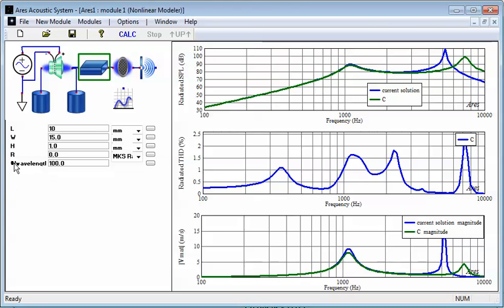That should be read as number of discretizations per wavelength in terms of the port. So if the wavelength is very long, you don't need many discretizations in the port. But as the wavelength gets short and you get multiple wavelengths in that port, you're going to end up with a lot of discretizations. In this case, the default is 100 discretizations per wavelength, which seems to work pretty well.